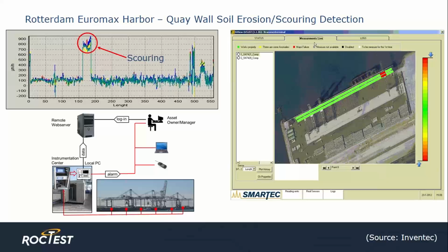In this instance, the length of 560 meters of cable with a spatial resolution of 1 meter yields 560 monitoring locations, many when compared to traditional instrumentation. Again, this was a fully automatic and autonomous system, sending alarm calls out when thresholds were reached.